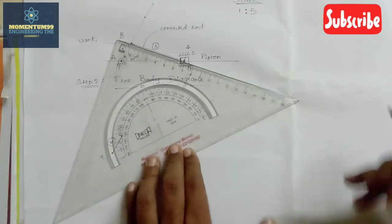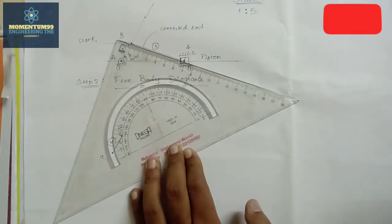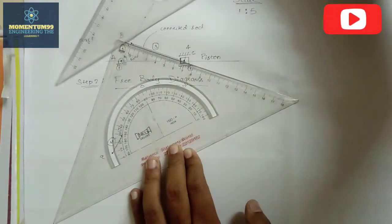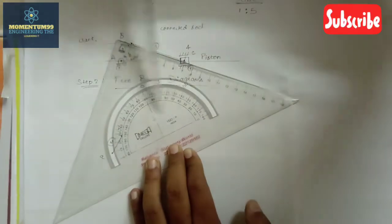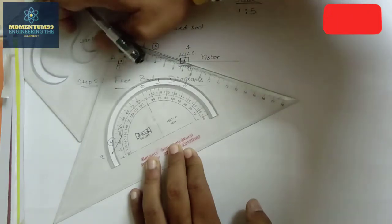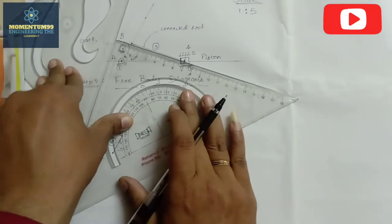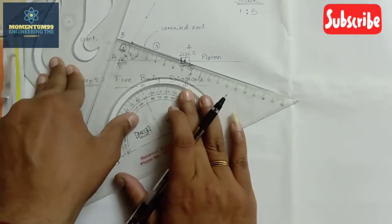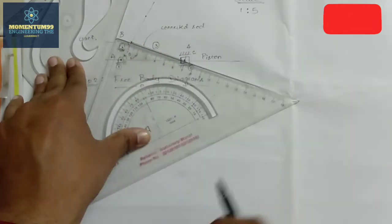Now next I will be taking another scale here, and I will be butting the scale at this end. Getting this? Now if I move the scale in the downward direction, I will be butting the two scales like this. Now this edge is parallel to this connecting rod here.